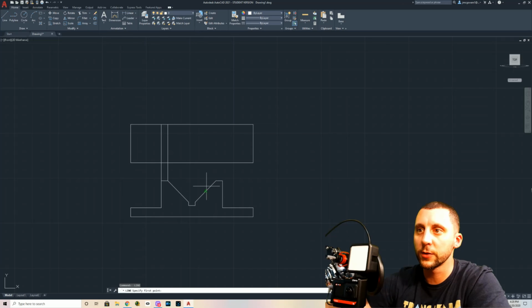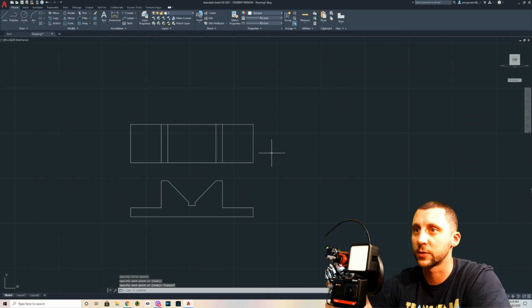And this bend, okay, every time you have a crease like that or a bend, you have to show that hard line. Now, I'm drawing these lines up, and that's going to make me have to trim them later, but you could also do the object snap tracking and polar with the intersection. If I go on this corner here, I can slide up on the green line, click when I get the intersection, and then draw up. You can do that as well. That saves you a step where you don't have to actually trim, okay?